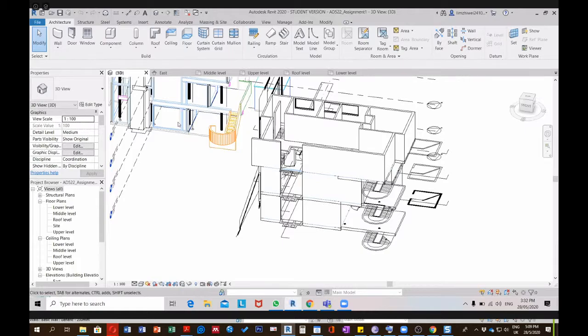Same thing for this one, I will delete this, click wall again, and go to pick. Now is this exterior or interior? It's exterior, so here it should be core exterior, core interior. See, but it will follow the whole wall. That's why sometimes we need to use this line, so we can stop here, for example. So these are all tools that you can use to draw walls.